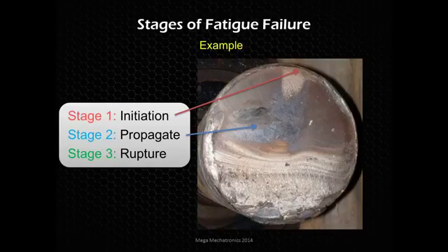And you could tell it was over time because there's rust. Look at that rust, that oxidized orange, dark brown surface. So you can almost tell that this has been propagating for a while. And then it gets lighter and lighter until we rupture down here, where we see sort of a brittle fracture. And we can make out how far those beach marks made it to that final point. So it almost went through three quarters of this shaft before it finally failed.